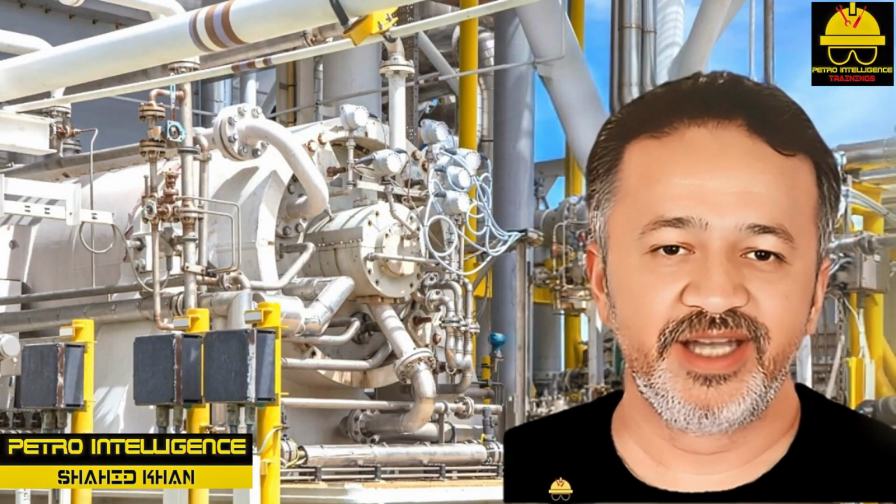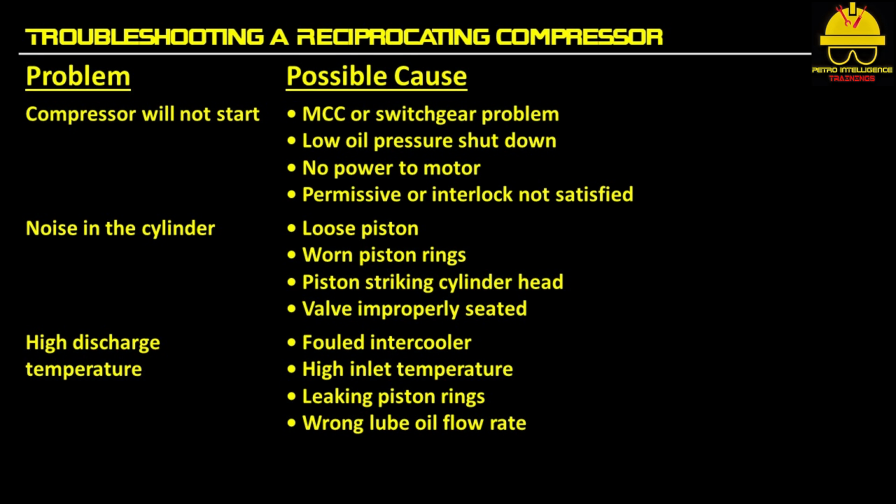Troubleshooting a reciprocating compressor. Compressor will not start if there is a MCC or switchgear problem, low oil pressure shutdown, there is no power to motor, or permissives or interlock not satisfied.